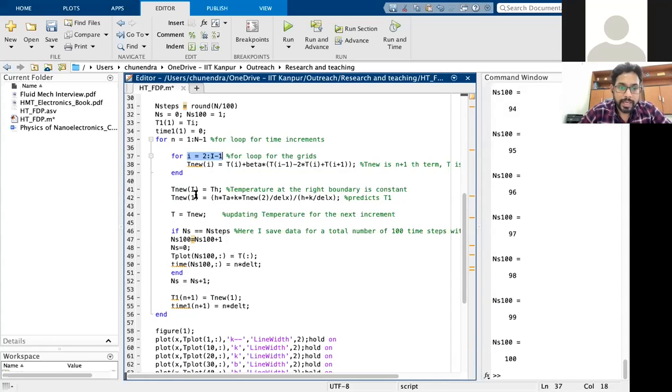All right. So once this part is done, that is calculated for that particular iteration, and now we go to the next iteration. By next iteration, I mean next time step. And when we go to the next time step, I update that T with T new. So I calculated T new, but for the next time step, that T new has become T old. So now this n plus 1th term has become n. So that T is updated, and this will be going back to here. You don't have to really worry about this part. This is something I did just for the sake of plotting, but the main concepts are here, these 4 lines.